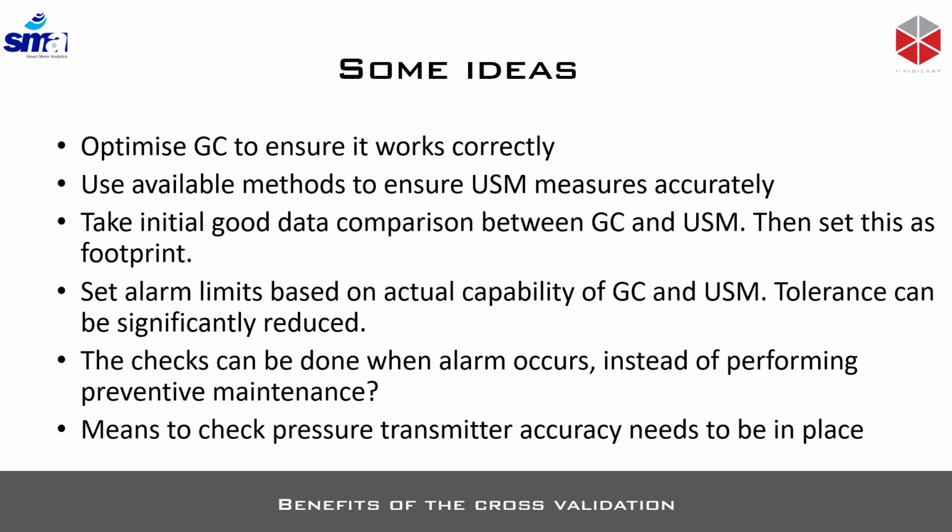Also, we need to make sure that there are means to check the pressure transmitter accuracy, because the pressure transmitter is the dark horse here. Basically, if we have an issue with the pressure transmitter, this method will not be able to identify that issue.